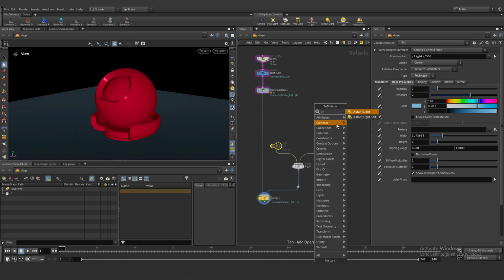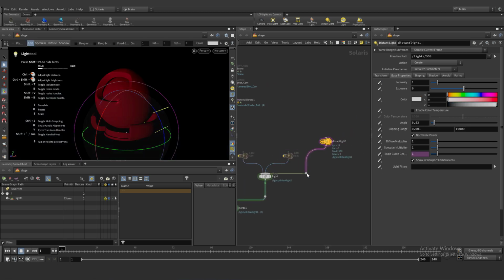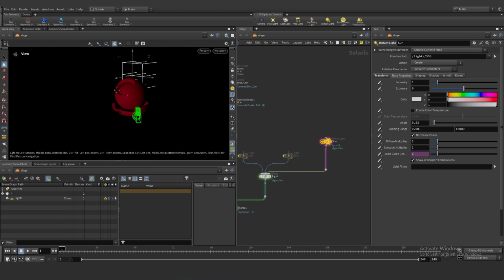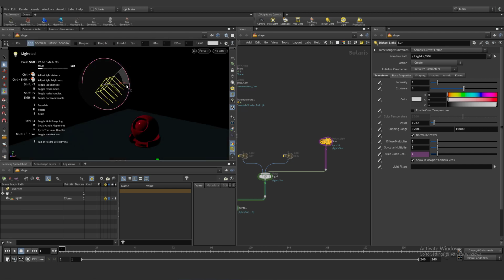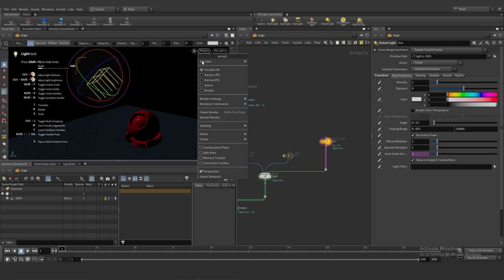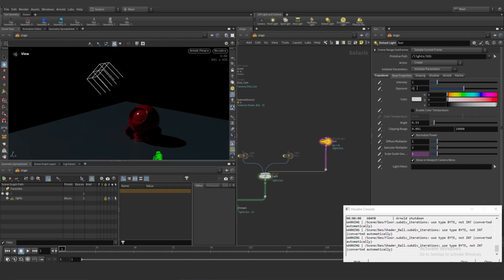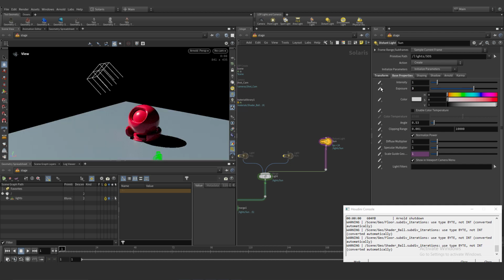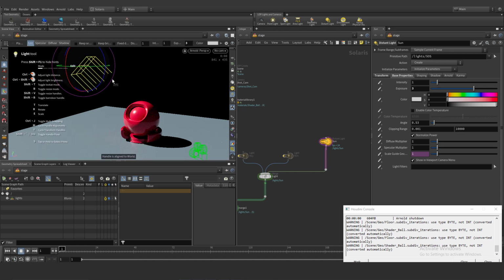Let's create distance lights. This is a type of light like the sun. If we rotate our sun, the light direction automatically changes, but if we move it, it looks the same because it's only for rotation, because it's infinite strength. It's the sun.